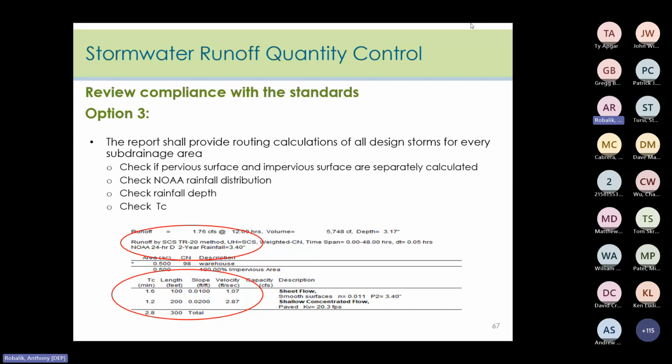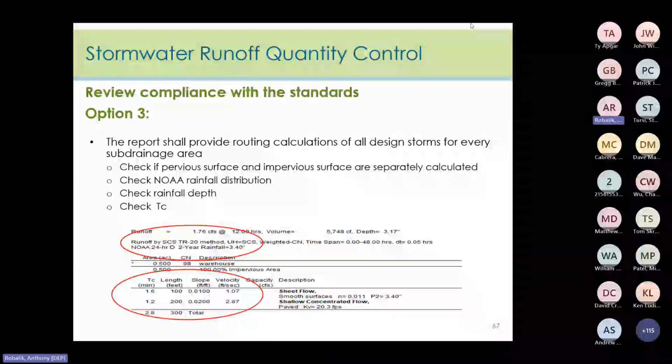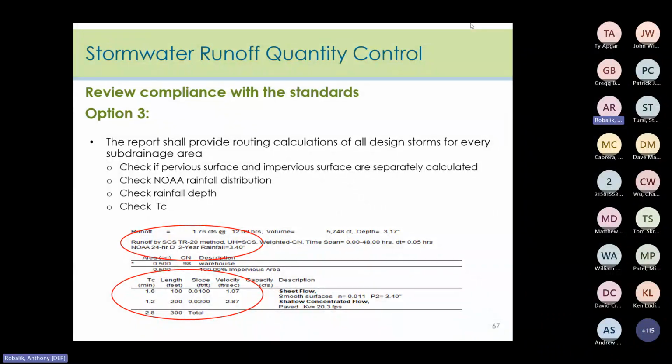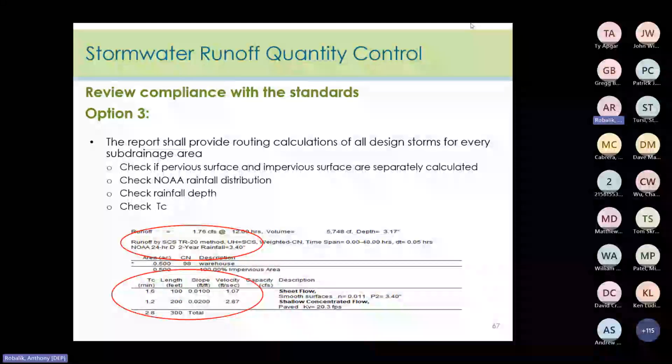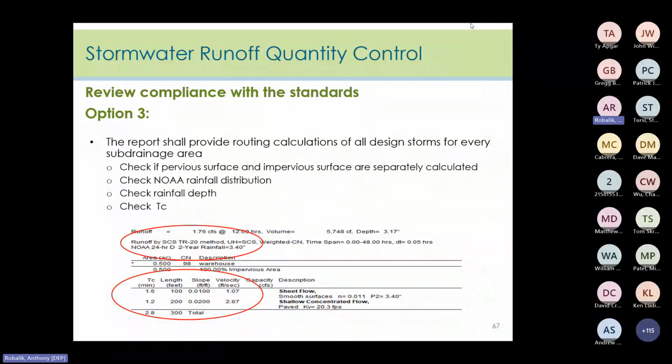And lastly, for this slide, check that the time span used captures the full storm event and discharge, and it isn't cut short. A lot of times we see the time span beginning at some time other than 0, or cut short when there's still a decent amount of volume left in the hydrograph. So we just want to see that the entire storm event and discharge is captured.